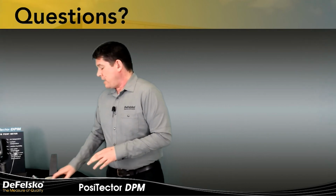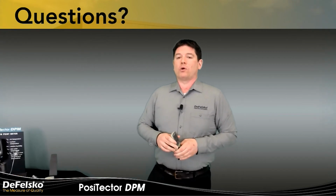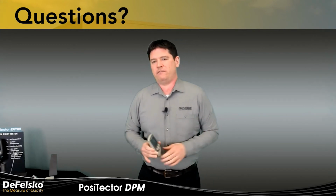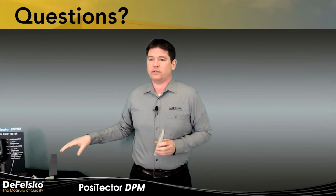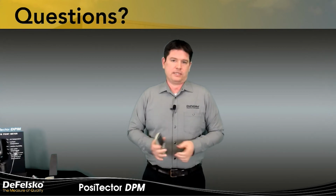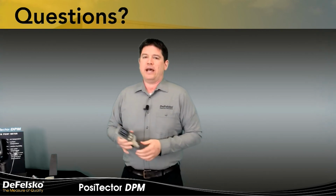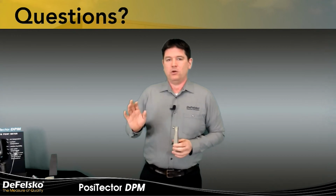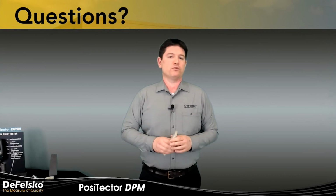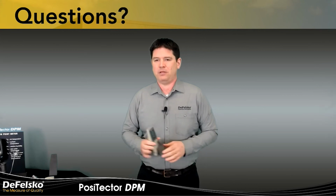The PosiTector DPM IR is great when you have very hot or very cold surfaces, or a surface that you can't quite make contact with. But one of the advantages of the regular PosiTector DPM is that you don't have to worry about emissivity or distance to spot ratio. It is something to keep in mind with the PosiTector DPM IR that you do have to know what the emissivity is in order to get a good reading on a surface. It does have a default of 0.95, which will work for most surfaces, but for some specific surfaces, you do have to know the emissivity, and that can be a little challenging.